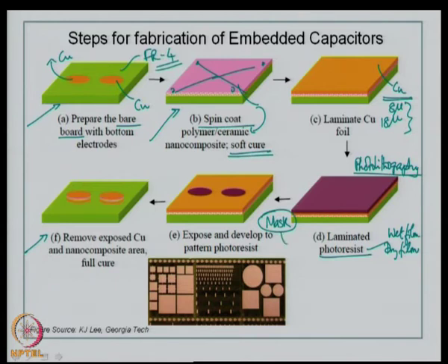The mask defines the capacitor pattern. Okay. So, now using the right mask, you expose and develop to pattern the photoresist using a suitable developer, and then once you remove the photoresist after the allied processes in between, you will now get a sandwich pattern of the two metal plates with the capacitor material in between.